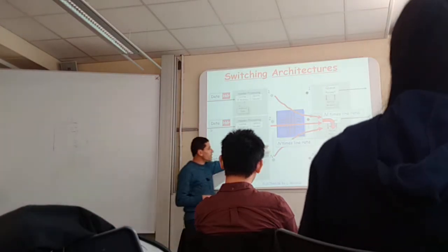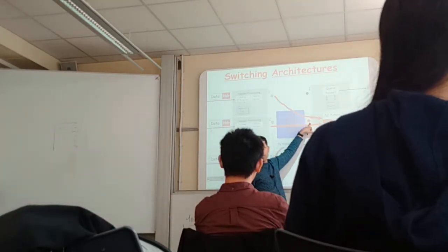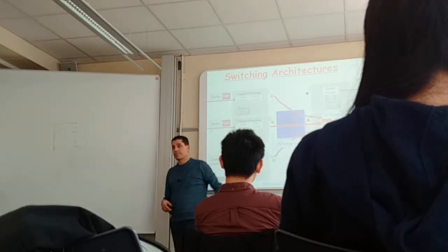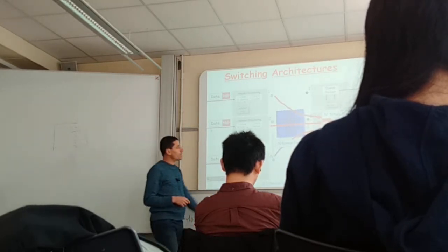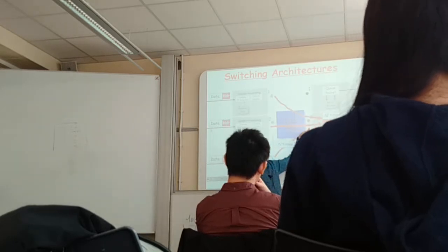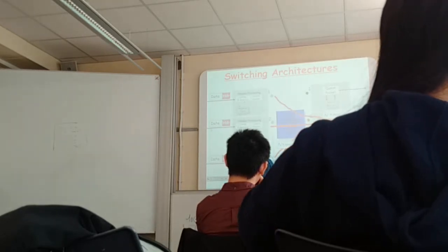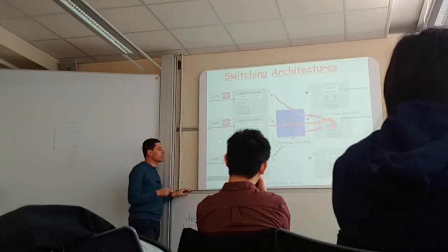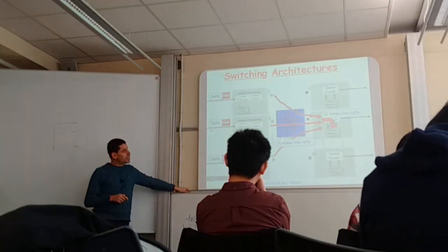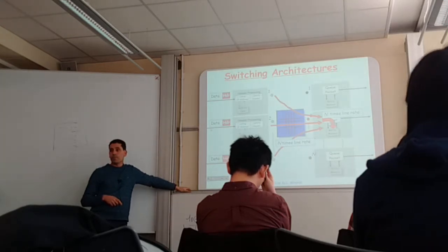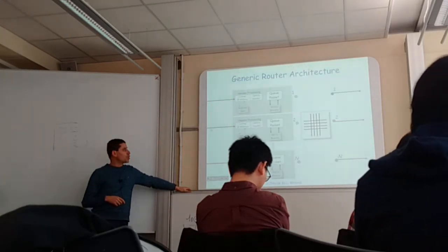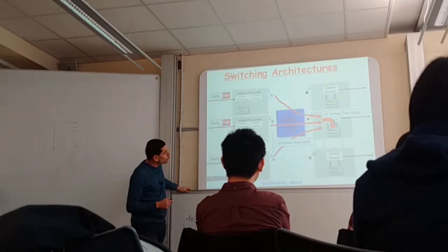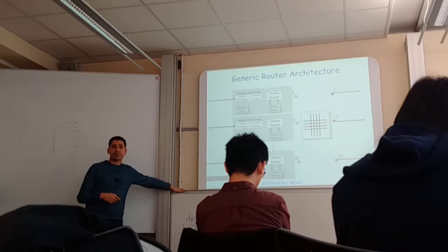Also, this is a bus. The interconnect must also work n times the line rate, because at some point the packets will be crossing a certain bus there, and that bus clock must be this. So it should pass the packets much faster than they come in, in order to sustain them, reaching that numerical speed. Clear? Good.